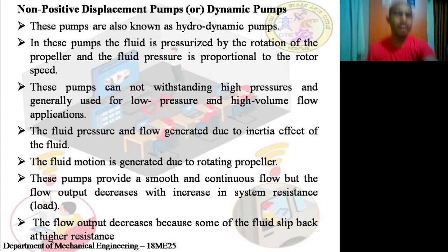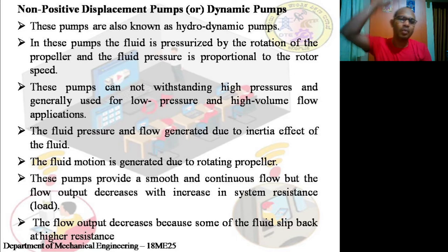And when you go for the third floor, fourth floor, and multi-storied buildings with 15, 16, 20 floors, then the same 1 HP pump will not be useful. What decides this is the power with which it rotates. Then we will have to go for a higher rotor speed pump, which gives more fluid pressure so that it can reach such elevations.